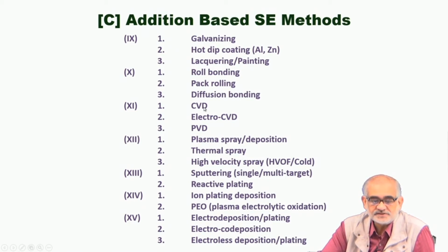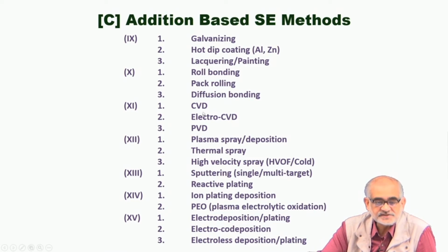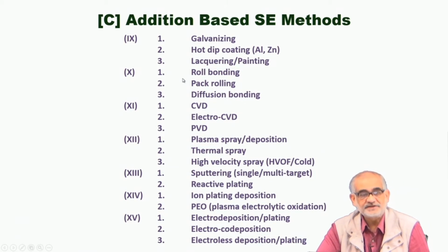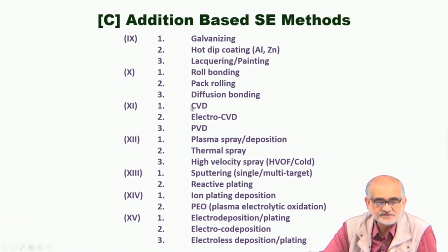So what you deposit is, composition-wise, slightly different than the precursor. The same thing can happen in electrochemical vapor deposition, but in physical vapor deposition there is no change in composition from the precursor to what you deposit onto the surface. So all these processes, 9, 10, 11, are processes where you would be adding on to the materials by changing the composition of the surface.